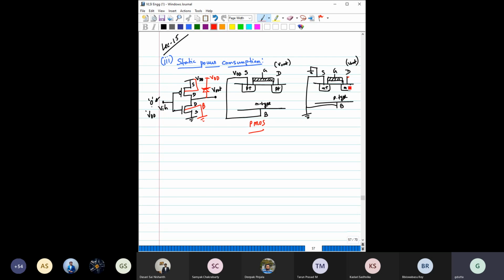Then that also makes this PN junction reverse biased. So we can illustrate this like this. I have to change the diode direction because here P is connected with the ground, so it should be like this. That way we can model this total phenomenon by introducing another diode here, right?